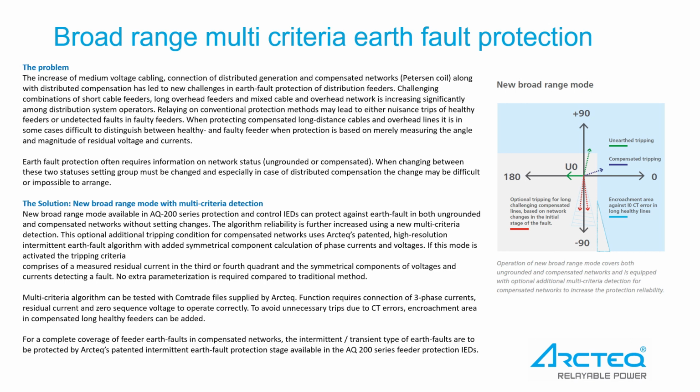For a complete coverage of feeder earth faults in compensated networks, the intermittent or transient type of earth faults are to be protected by Arcteq's patented intermittent earth fault protection stage available in the AQ200 series feeder protection IEDs.